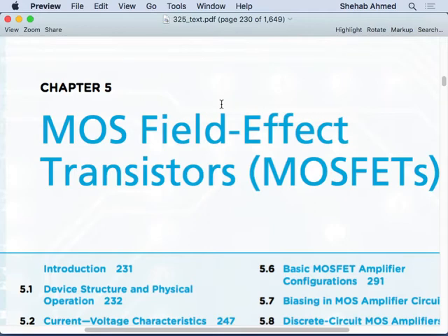But the diode itself is a two-terminal device. The current that's flowing is the current that's actually controlling the device, and it's the actual current that is flowing in your load as well, right? So you have a device that is controlled by the external circuitry, and the current that's flowing inside you don't have too much control over, except very limited small signal control.